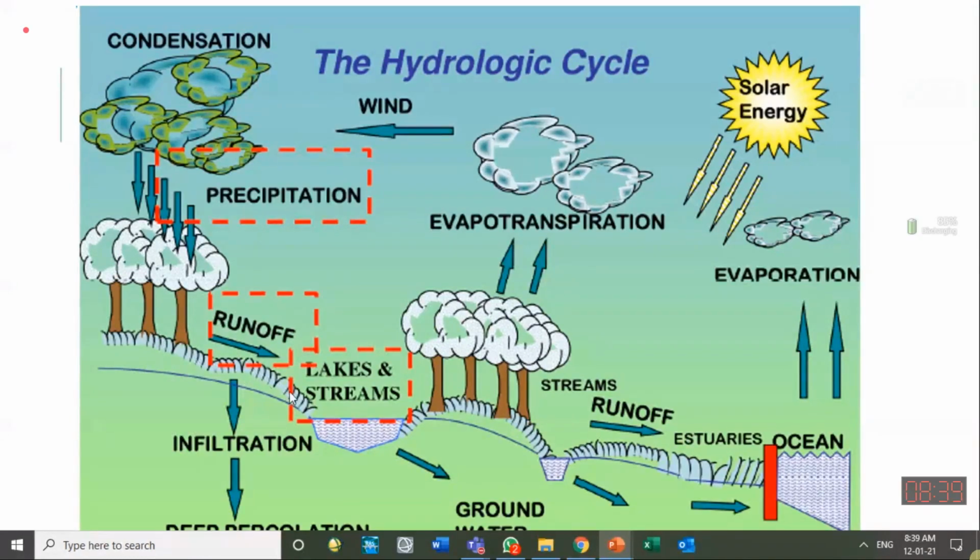From the unsaturated area, water flows towards the stream, downhill, and water flows from the ground surface also. Ground water is not stagnant. Its flow is slow. It is not as fast as the surface flow. It is a slow flow, but it is flowing towards the gradient. Gradient means the slope of the water table line. So it is moving towards the gradient.